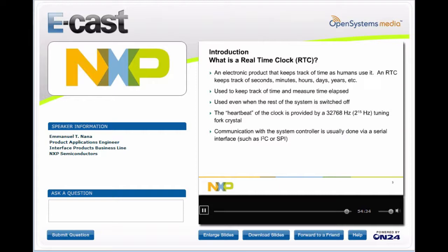But without that information, what I did was say, using NXP's real-time clock, this is how long it would take to deplete the battery. That way, that can be compared with other devices for an apples-to-apples comparison. But basically, that just says with NXP's real-time clock running off this battery, this is how long the battery life is.